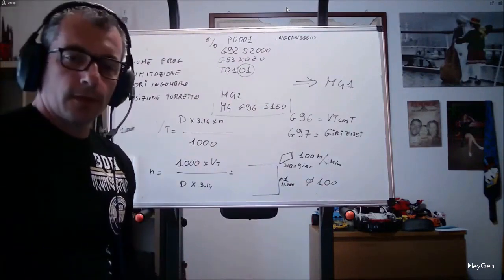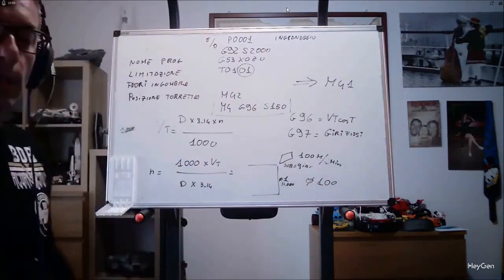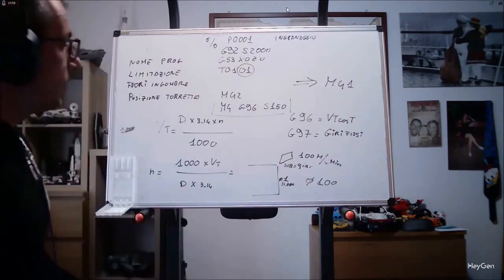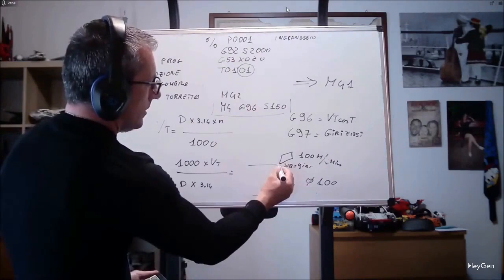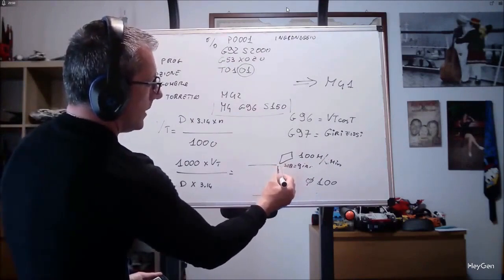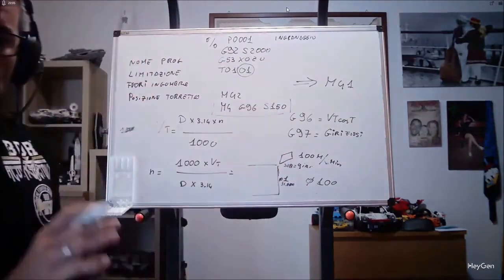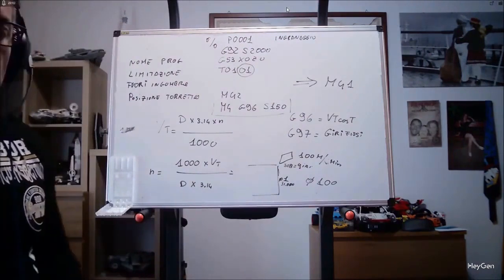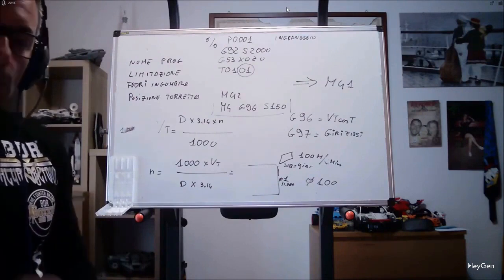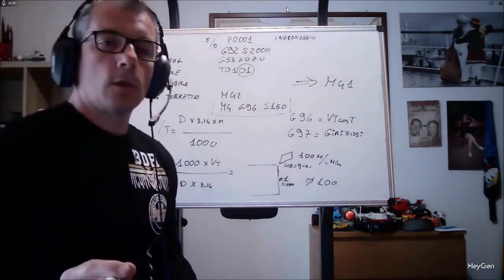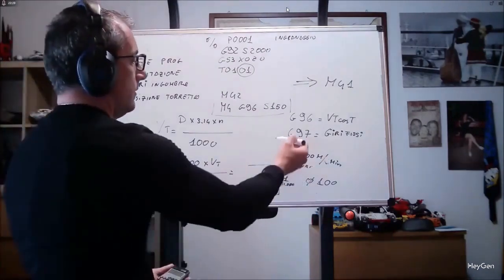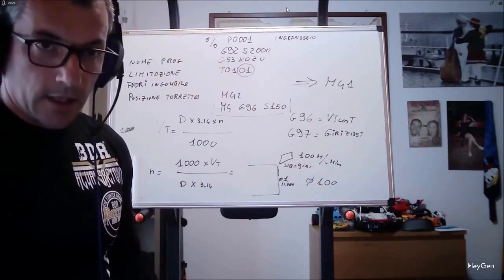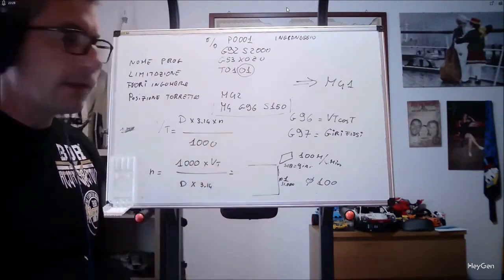It is quite obvious that a lathe, perhaps of large size, at 31,000 revolutions will break apart. You will find screws on the ground. That's why the machine will slow down. It will increase its revolutions as it approaches the center until it stops here. Here is the difference between constant cutting speed and fixed revolutions. If you are already working in the workshop, just perform a facing operation to physically feel the machine accelerating as it works towards the center.